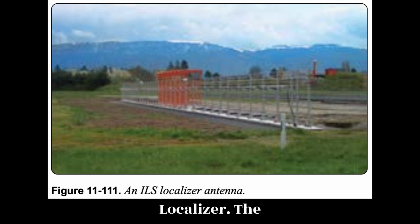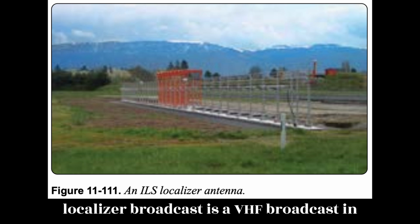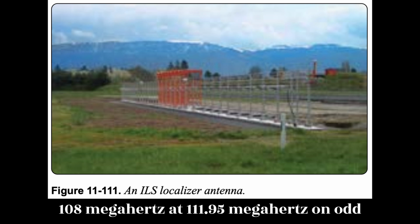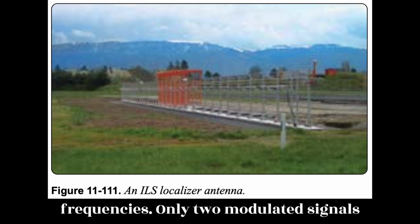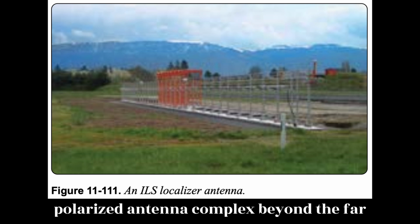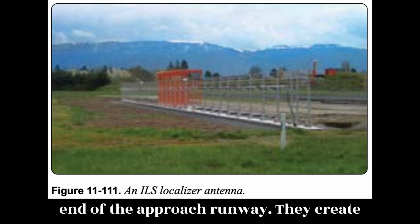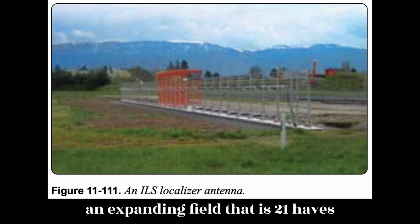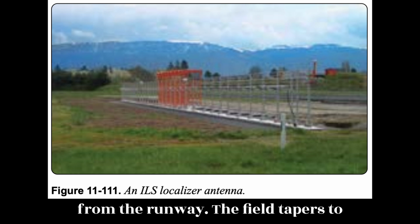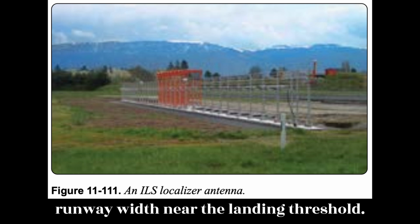Localizer. The localizer broadcast is a VHF broadcast in the lower range of the VOR frequencies, 108 MHz to 111.95 MHz, on odd frequencies only. Two modulated signals are produced from a horizontally polarized antenna complex beyond the far end of the approach runway. They create an expanding field that is 2.5 degrees wide, about 1,500 feet at 5 miles from the runway. The field tapers to runway width near the landing threshold.